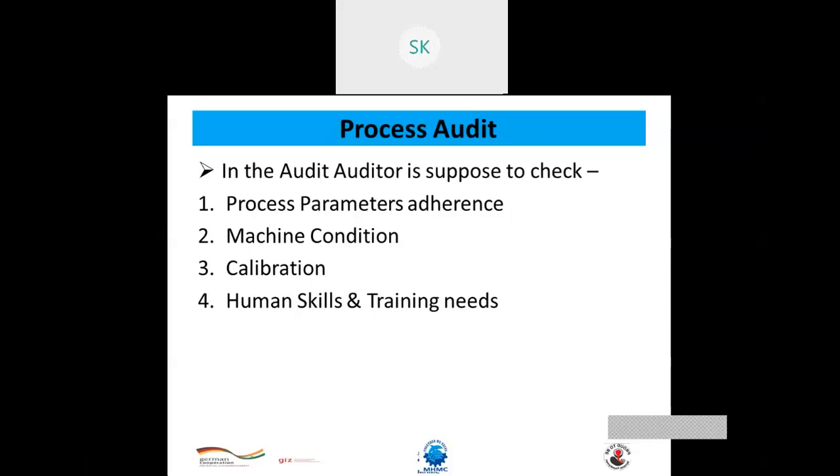Many times on paper there are 3 dies, but when we go to the audit on the shop floor, we see there is only one die, and it is in a very bad condition. It is almost black in color. There are a lot of damages, a lot of hammering has been done, there is a gap between the parting line, and metal is going out from the parting line. All these things we find on the shop floor. If this is the condition, how can we expect our spectrometer to show exactly correct readings for the chemistry?